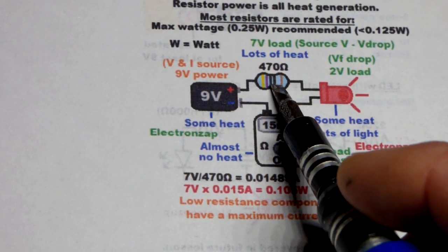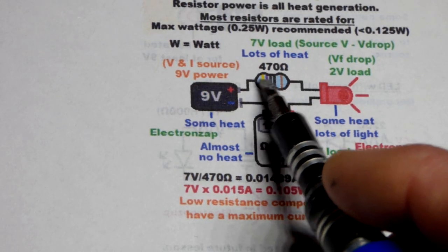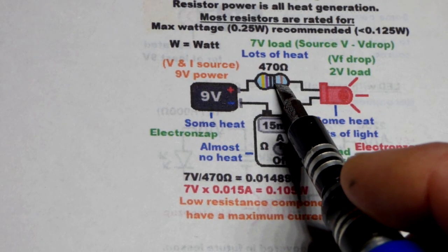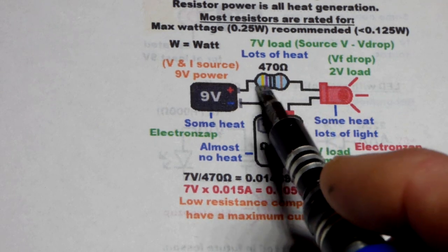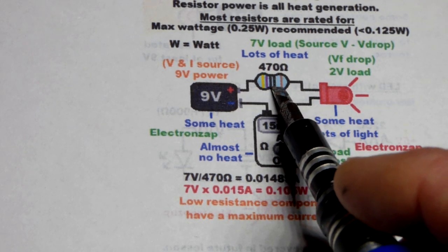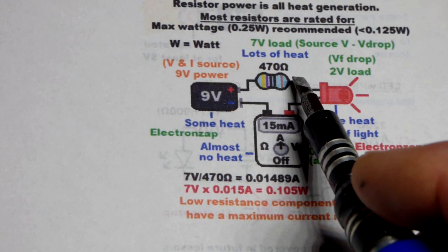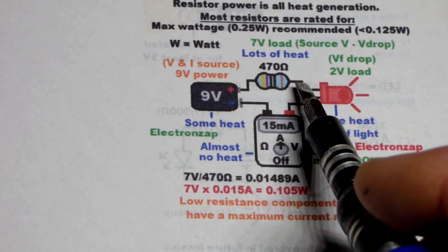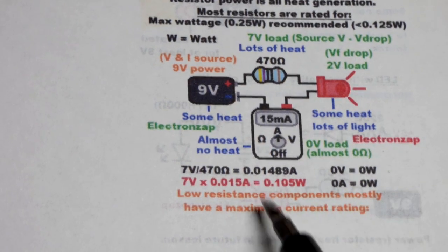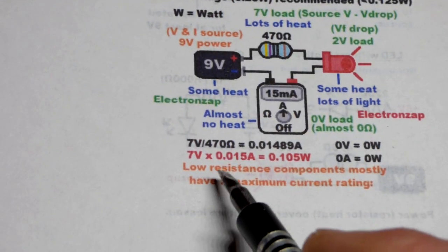They take whatever voltage comes across them, and if you put multiple resistors in series, they'll actually divide up that voltage based on their resistance. But they pretty much just accept whatever voltage ends up across them, and that will put the current through them. They are related. That's what we did right there with Ohm's law.